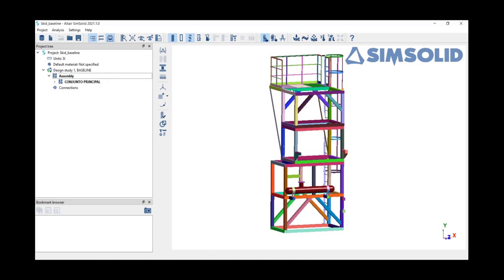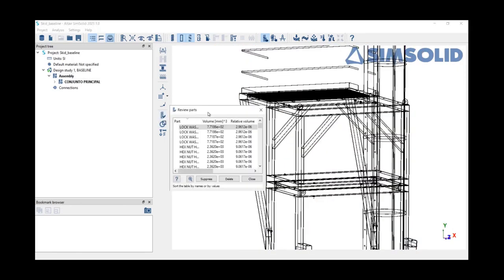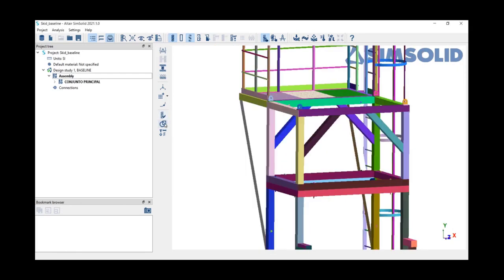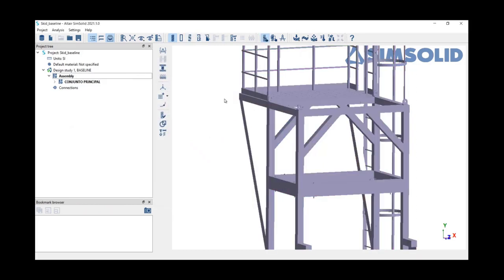As opposed to removing every single small intersection, you'll notice when you go to the geometry checker that it will tell you what kinds of overlaps and such you have. These small overlaps are going to end up being acceptable. The solver is going to be able to handle this so long as they're brought in as separate parts and not as one big merged component.